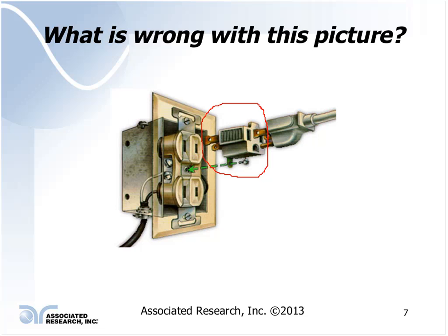And one thing you'll see, many of these devices either have a wire coming off of them, or have this tab down here that is designed where they tell you to remove the screw from the cover plate, and ground this to this cover plate, or to the receptacle whenever you're using one of these to provide a ground connection. That may be a very big fallacy depending upon the outlet that you're plugging your device into.